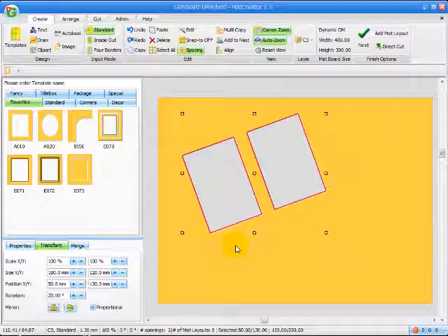Mirror is very handy when you want to, for example, create a multiple opening layout, and there's elements of symmetry in the multi-opening where you could then, say, create the left-hand side only, then copy everything on the left, then mirror that over and paste it again. So you could literally halve the amount of time you spend creating a multi-opening just by using the mirror tool.